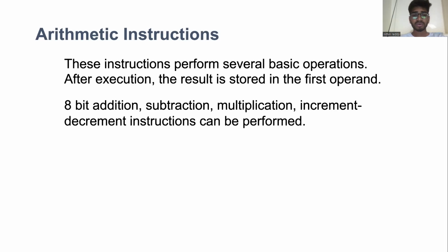Instruction register. This holds the instruction which is to be decoded. Program incrementer: this 16-bit register keeps incrementing the address according to the program flow. Program address register. This is a 16-bit register. It holds the address of the code to be accessed.